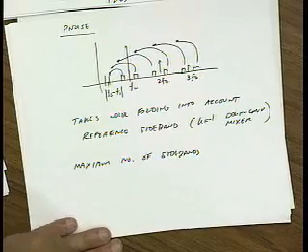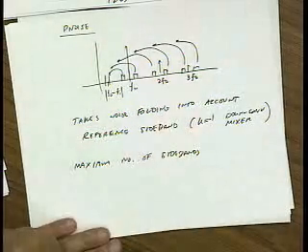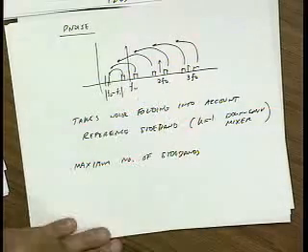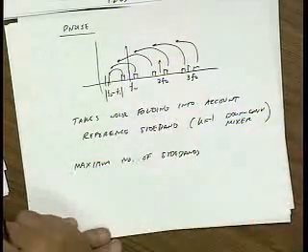So if you're really interested to know how much noise folding is going on, you could start out and say, just include the noise from the first sideband. Then you could say, now add the second sideband and the third sideband, and you'll see the noise figure go up step by step.